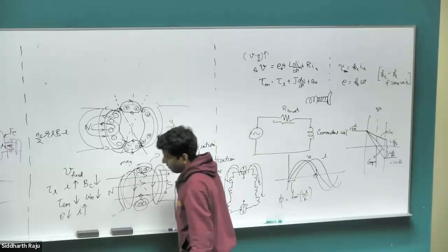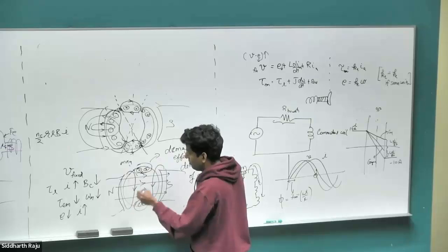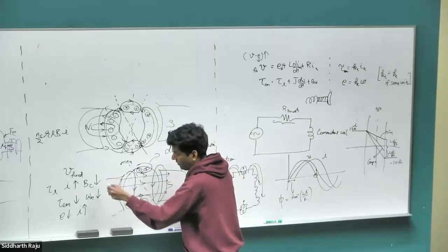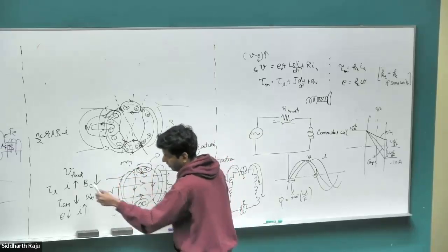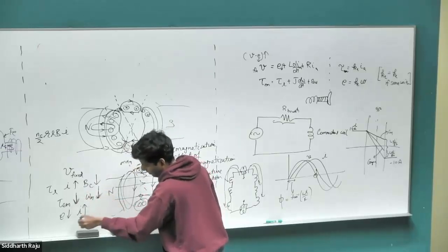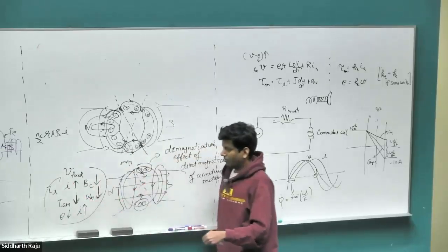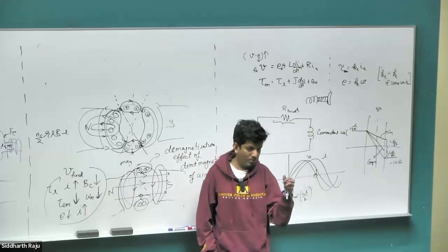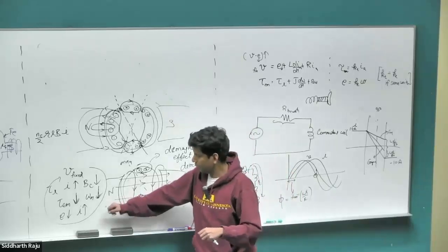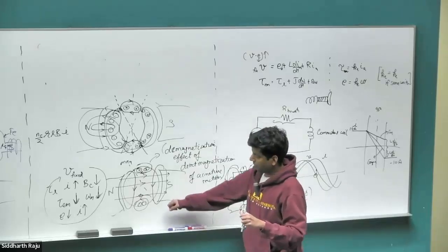We have set up a cyclical loop. Now again, this I increases, B starts to reduce, and it gets compounded even worse because as I starts to increase, the core starts to saturate more and more. So the amount of reduction in the B starts to increase as well, even though the I is increasing. So then the B reduces, then the tau EM reduces, omega reduces, E reduces, I increases, and it becomes a cyclical loop, especially in very high power motors, where when you go to very large rated torque or slightly above rated torque, it goes into a stall condition where it abruptly comes to a stop. So this goes into an unstable operating point. This demagnetization effect of this direct magnetic field is extremely problematic in very high power motors.